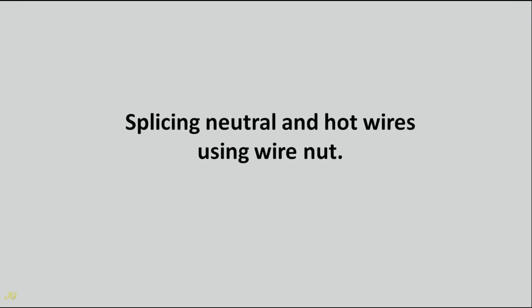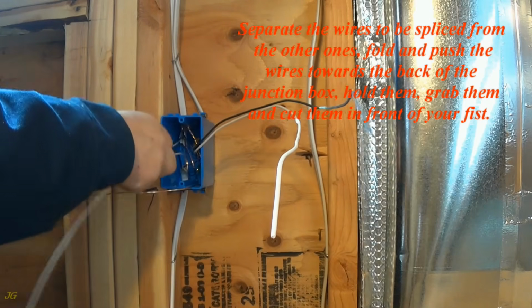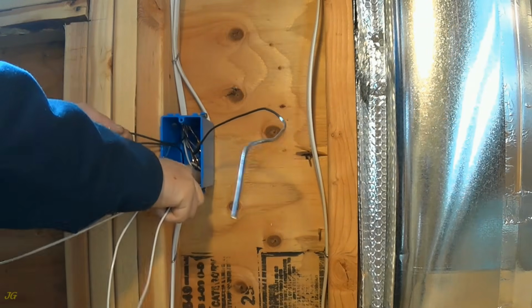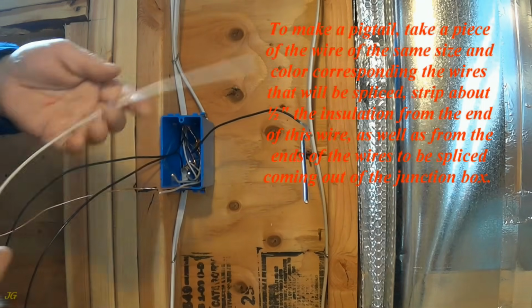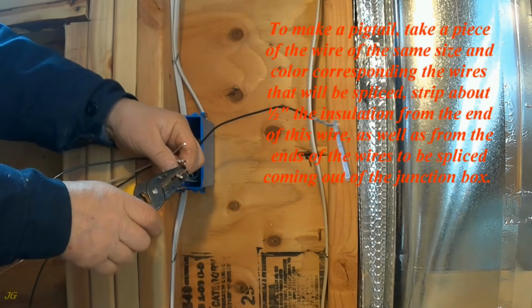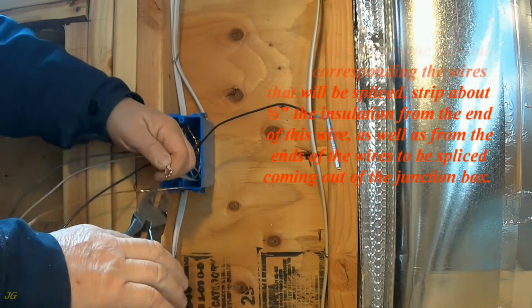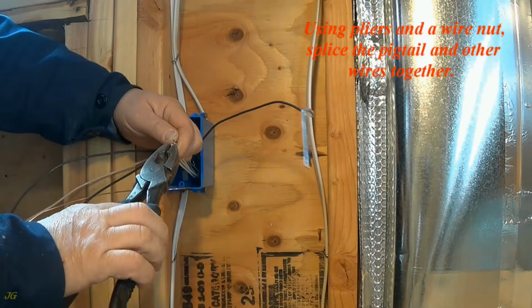Splicing neutral and hot wires using wire nut. Separate the wires to be spliced from the other ones. Fold and push the wires towards the back of the junction box. Hold them, grab them and cut them in front of your fist. To make a pigtail, take a piece of wire of the same size and color corresponding to the wires that will be spliced. Strip about 1/2 inch of the insulation from the end of this wire, as well as from the ends of the wires to be spliced coming out of the junction box. Using pliers and a wire nut, splice the pigtail and other wires together.